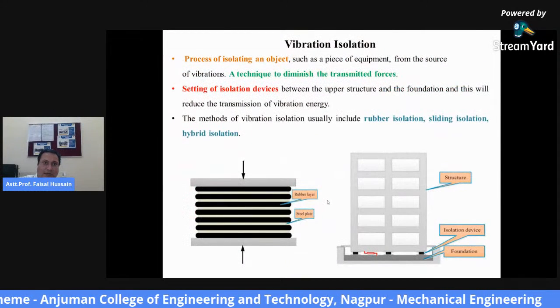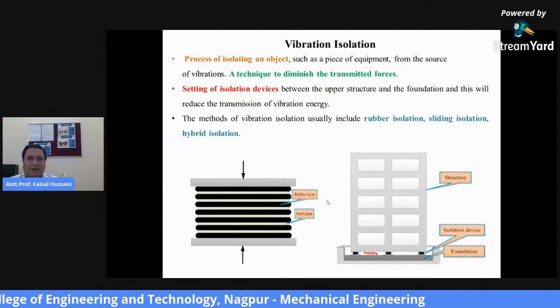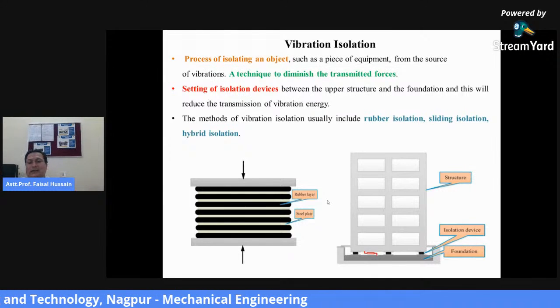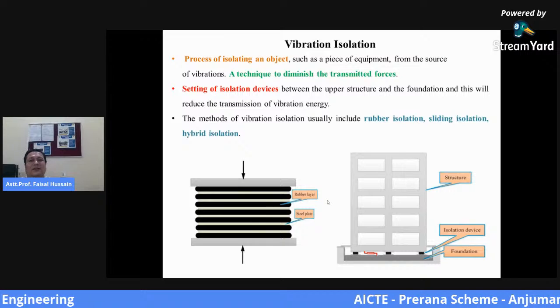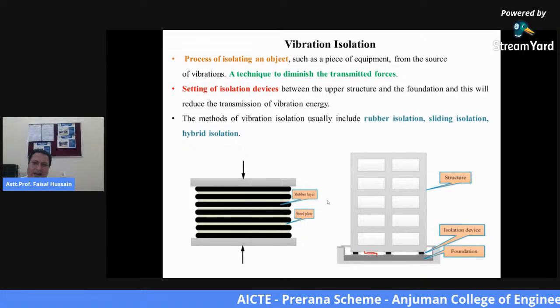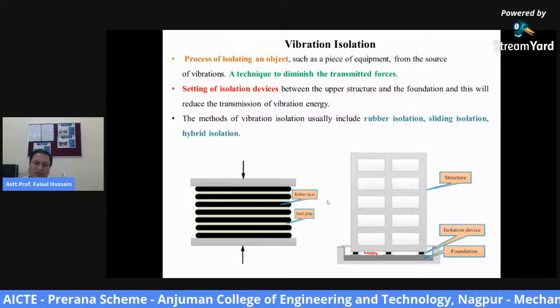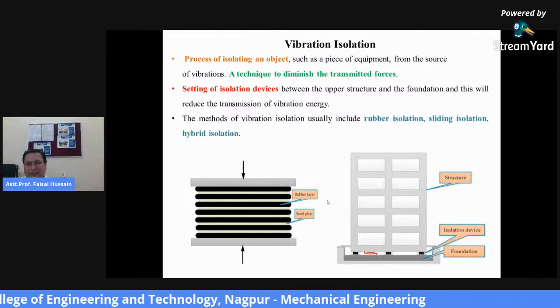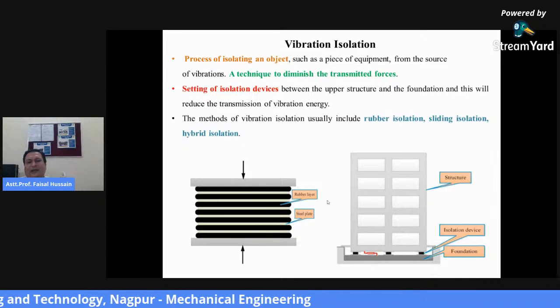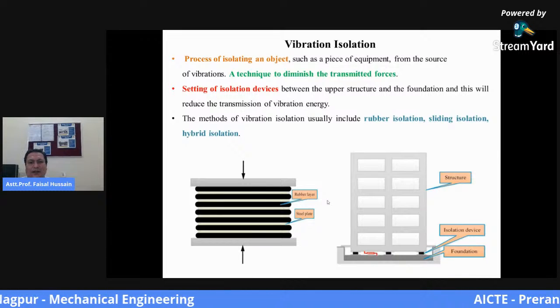Now let us move to the next part, vibration isolation. In simple terms, it is a technique which is used to diminish the transmitted forces. In every structure or equipment there is a foundation, and when the equipment is in working condition, forces will be transmitted to the ground.